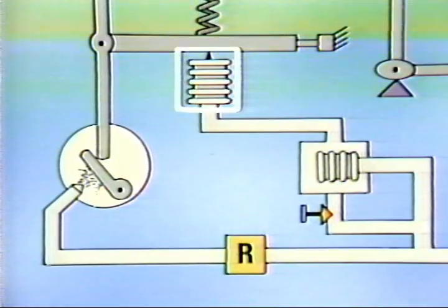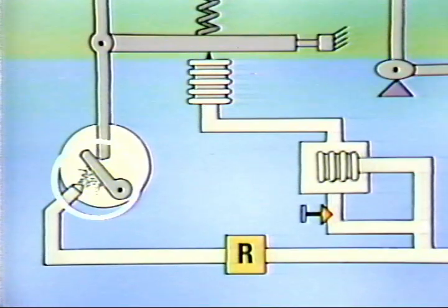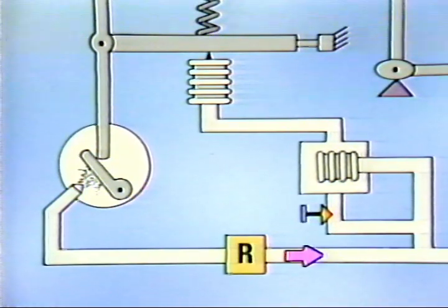When the output is delayed in reaching the feedback bellows, the flapper can remain close to the nozzle. This enables the controller to provide a boost in its output, which is the essential characteristic of rate control. This restriction is the controller's derivative time adjustment, which varies the amount of rate action the controller will provide.